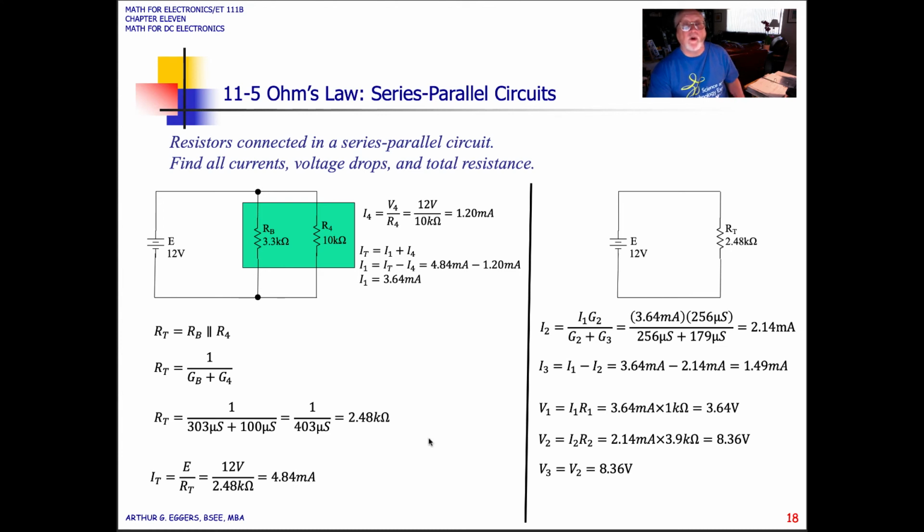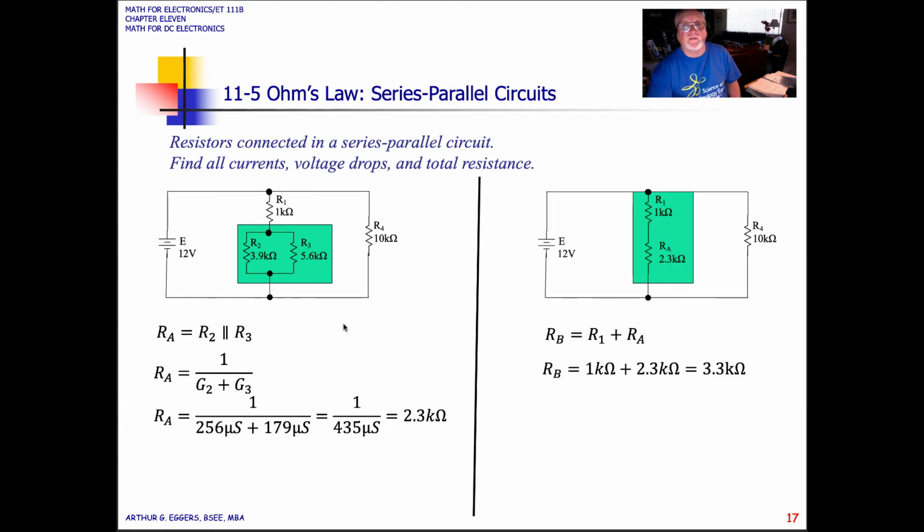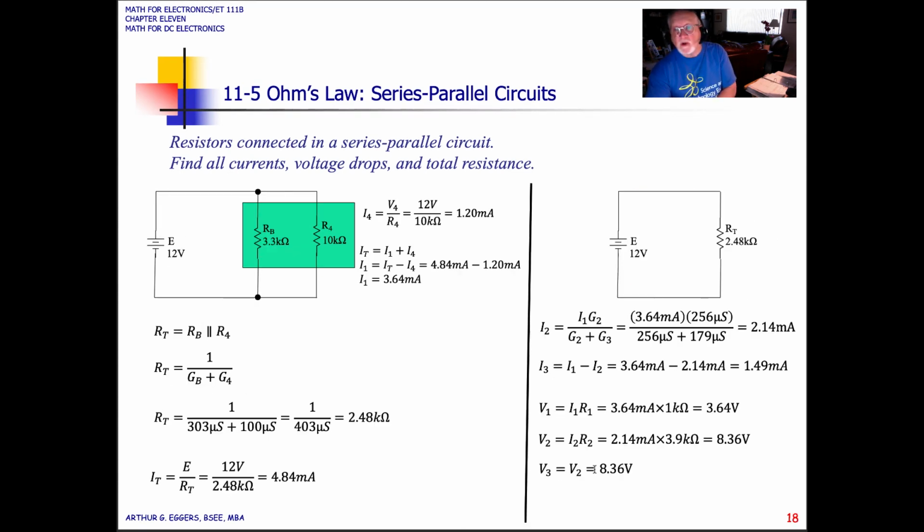Now if we want to go back and solve for the currents through each of these, I've got a current that hits this node, goes through R1, splits into two values, goes through R2 and R3, and back here where it joins up with the leftover current from R4 and becomes our total current back into the source. So in this expression then, we look again at the proportionalities.